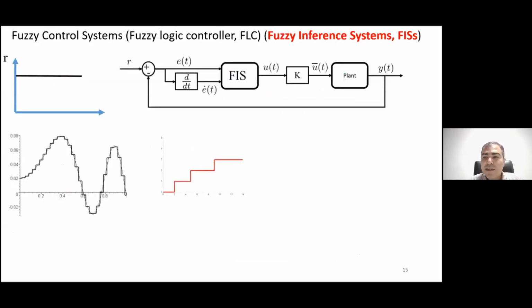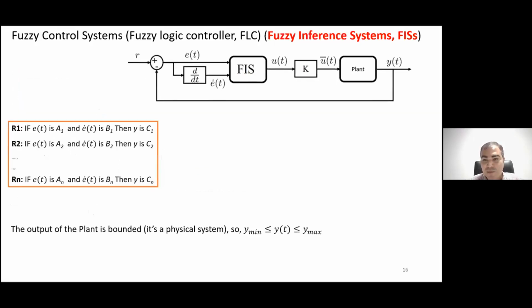For the sake of simplicity here, we consider a set point, a constant, as the reference to be tracked. For example, it may be the unit step. The unit step is indeed important because if a system has a satisfactory step response, then it is expected to have a satisfactory response to the other references. The reason is that almost any function can be well approximated by a combination of step functions.